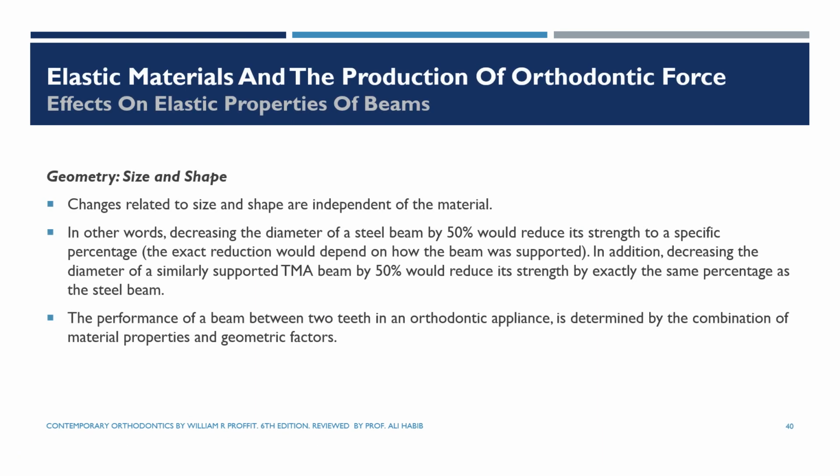The properties that we described earlier of any wire, the stiffness, strength, and range, could be greatly affected by changing the geometry of the wire, whether the size or the shape, round versus square versus rectangular, or 12 mil, 14, 16, 22, and higher sizes of wire diameter. They are also greatly affected by the length of the wire between the two supports, like in the model of beams supported from each side or a cantilever spring.